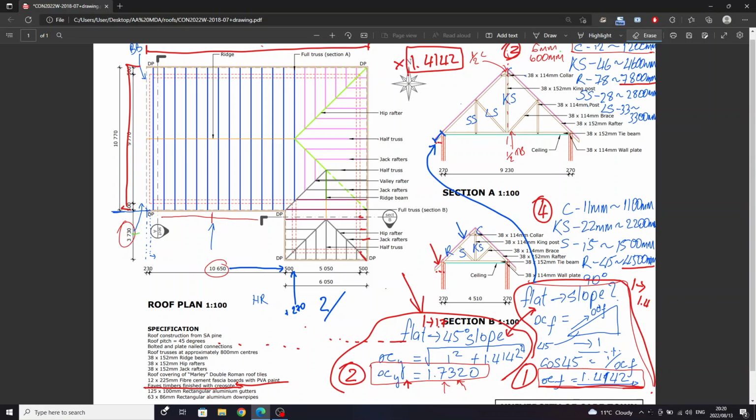And the creosote is quite a big calculation. The description is pretty short, but the calculation is long because you have perimeters of multiple exposed timbers, and the worst part is that it's not all clear on the drawing what is exposed. We've already done a little bit of investigation to find the tilting fillets and the battens, and then further investigation for the rafter ends and the hip rafter ends. So there's quite a bit of timber that's actually exposed here.